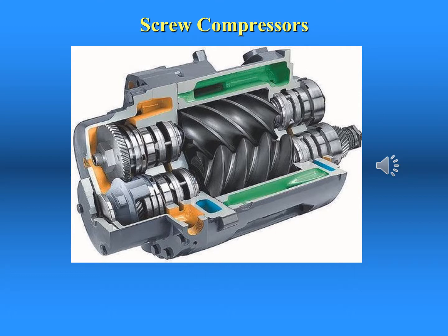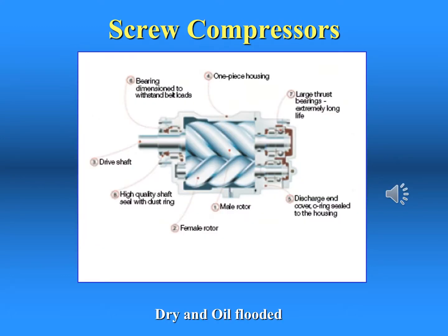Rotary screw air compressors are displacement compressors and are the most common types of compressors used for industrial applications requiring over 30 horsepower. Air comes in through a valve, typically called the inlet valve, and is taken into the space between the rotors. As the screws turn, they reduce the volume of the air, thus increasing the pressure. There are rotary screw air compressors with just one screw as well.